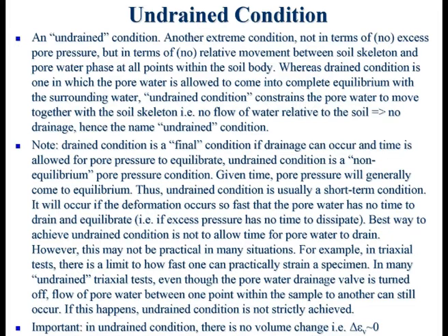So you are telling Mother Nature, or telling the computer program, telling the soil, I want your pore pressure to be in equilibrium with these boundary conditions. Fine. Now, if you specify it like this, then water will flow freely in and out. If there's any, it will flow. But then you cannot control the volume of flow, the volume flow rate.